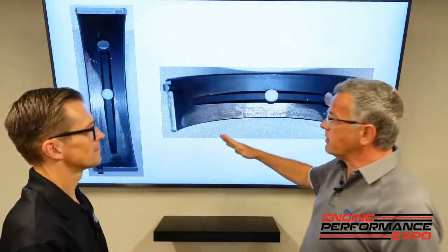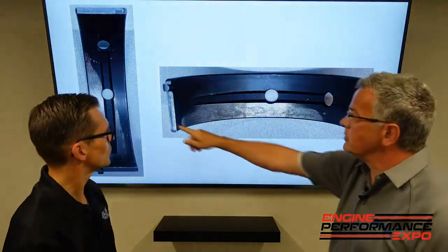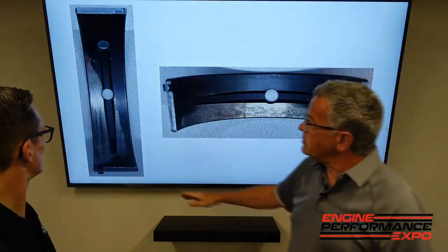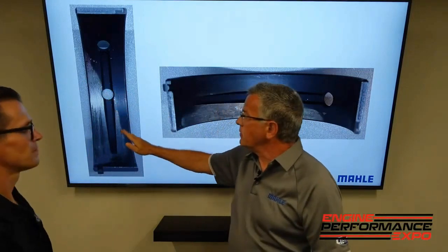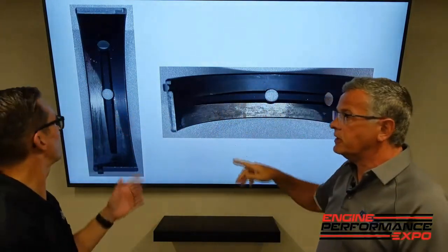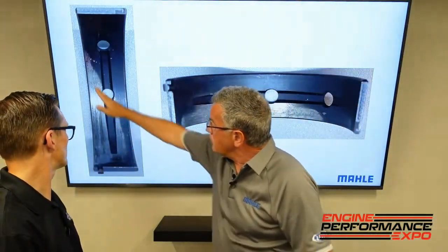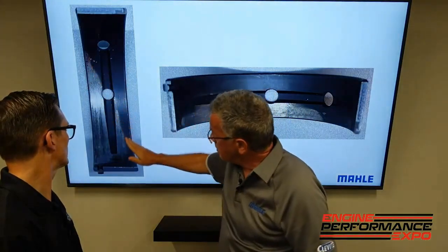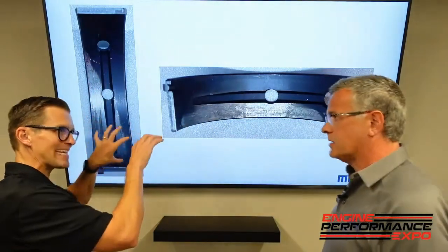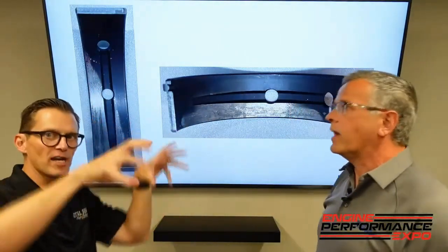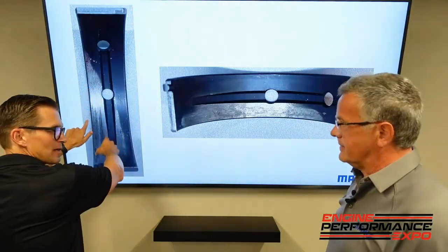So this is a typical LS bearing. I love this picture because there's so much happening in here. Same engine, number 2 and number 4. But you notice how this part of the bearing looks very good, and there's an angle. This is an upper. Notice most have grooves. So in this case, we have the crank bending up. Right. So you're getting fatiguing. You're getting deflection at an angle on the upper, because this is where that clearance is being taken up by the bending of the crankshaft. The dynamic motion of the crankshaft is taking up that running clearance and compromising the oil film locally.